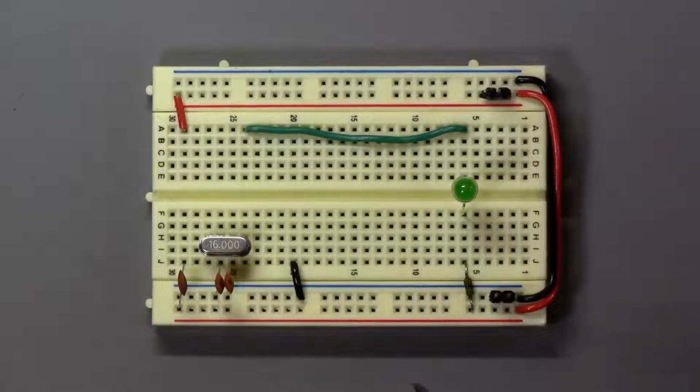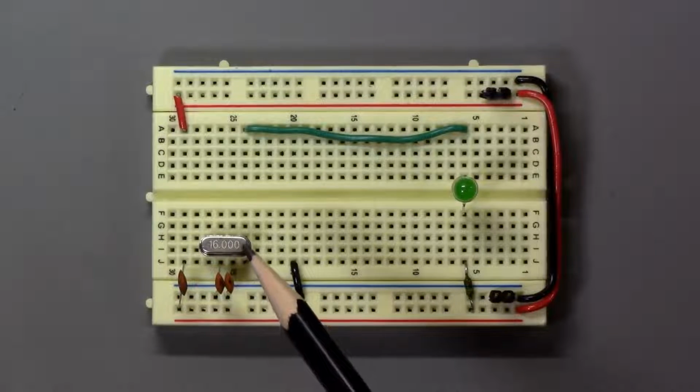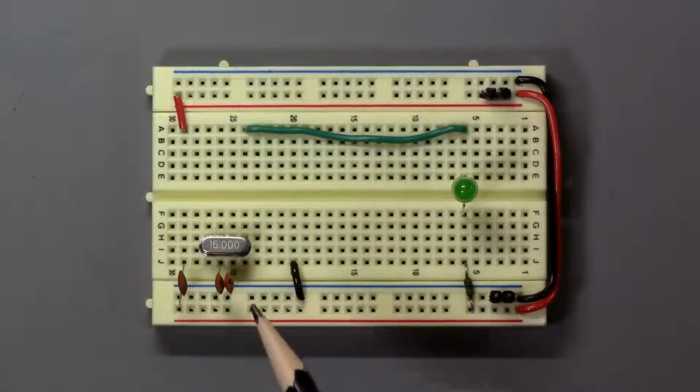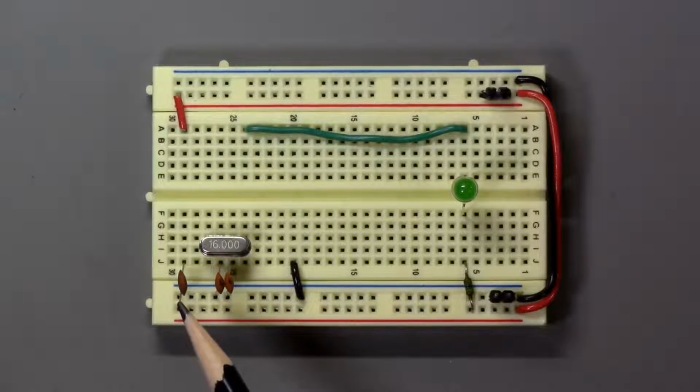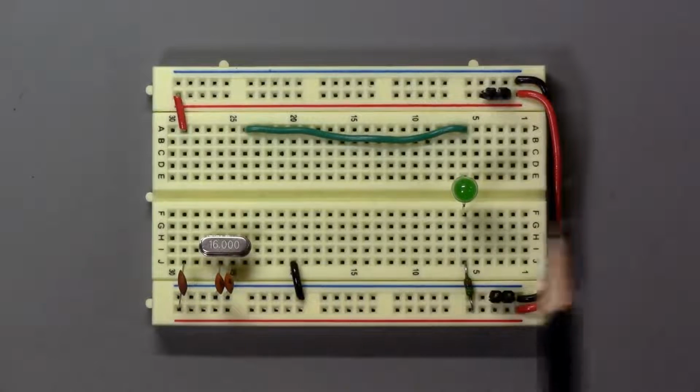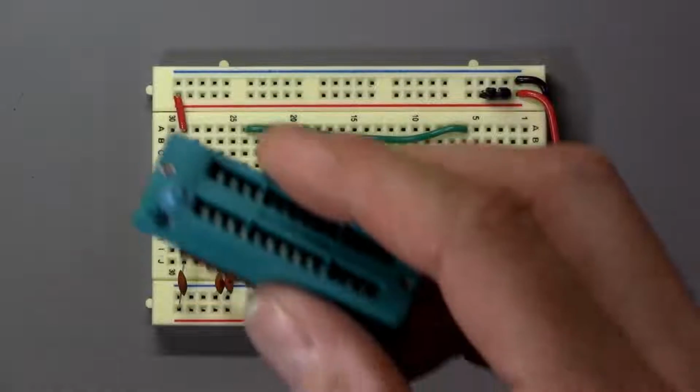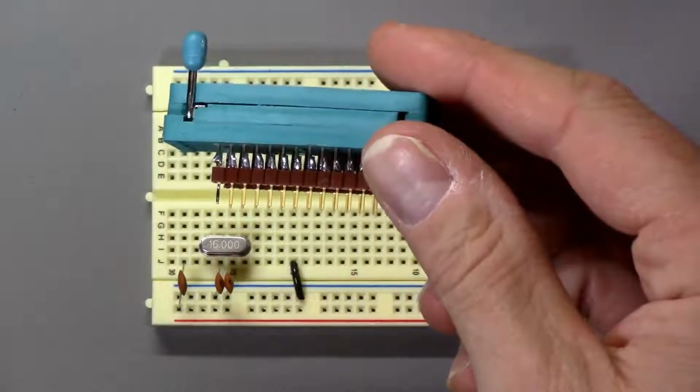All right, so here's the breadboard we're going to use for our circuit, and you can see the 16 megahertz oscillator here with the two 22 picofarad capacitors. This is the 100 nanofarad capacitor that's used to generate the initial reset pulse. And the actual IC for the microcontroller, I'm going to put in this ZIF socket, and as you can see,